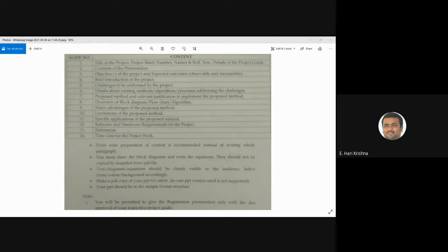In either case, you have a red LED, an IR LED, and on the opposite side you may have a photodetector. When the red and IR light pass through the finger tissue, the variations in the light can be detected by the photodetector, leading to a photoplethysmographic signal.